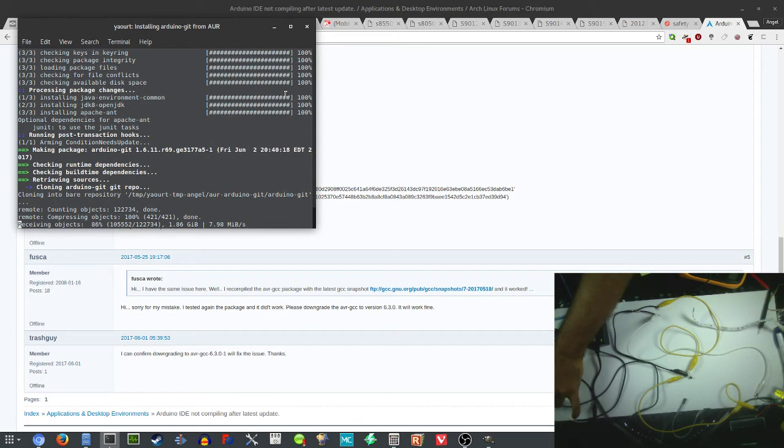That's because if I connect it to any pin in the Arduino, it's floating. It doesn't really know whether it's grounded or what. So I can pick the ground pin and try and see if I can get it to...